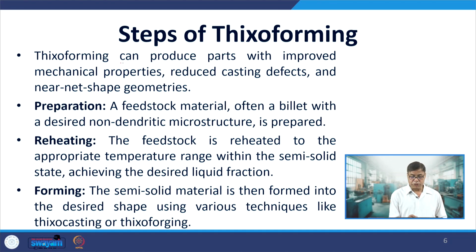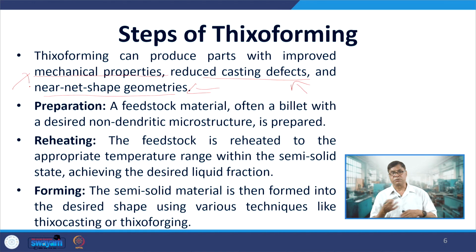Okay. So, thixoforming, because of the non-dendritic feature of the products produced through it, the parts show improved mechanical properties, reduced casting defects, and near net shape geometries. So, this will be reducing the machining, increasing the soundness, and improving resistance to the loads during service in the form of improved mechanical properties.